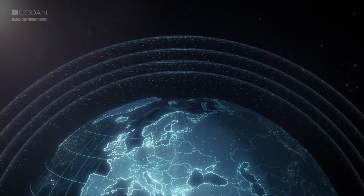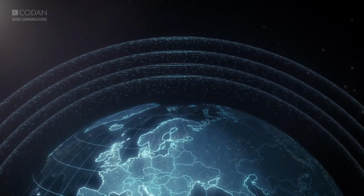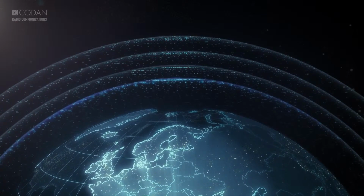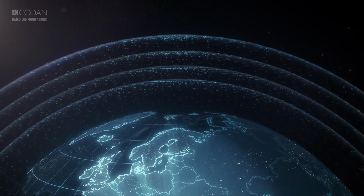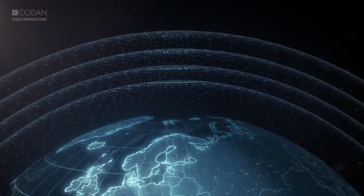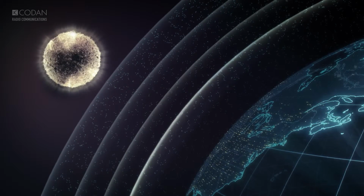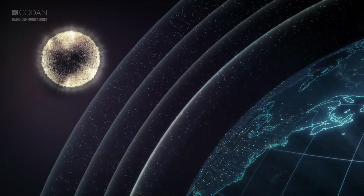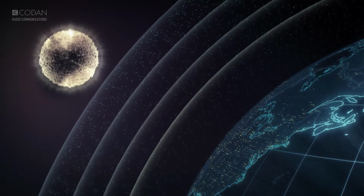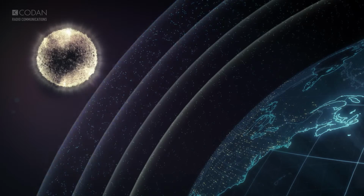The ionosphere itself is made of several different layers that refract the HF radio waves in different ways. These range from the closest layer that exists in the day, called layer D, to the farthest layer called F2. These different layers behave differently in the way that they refract HF radio waves. The D layer, in particular, can weaken or attenuate the HF radio waves, as it contains a higher number of charged particles due to the sunlight. The most common layers used for signal propagation are the F1 and F2. These layers change between day and night.